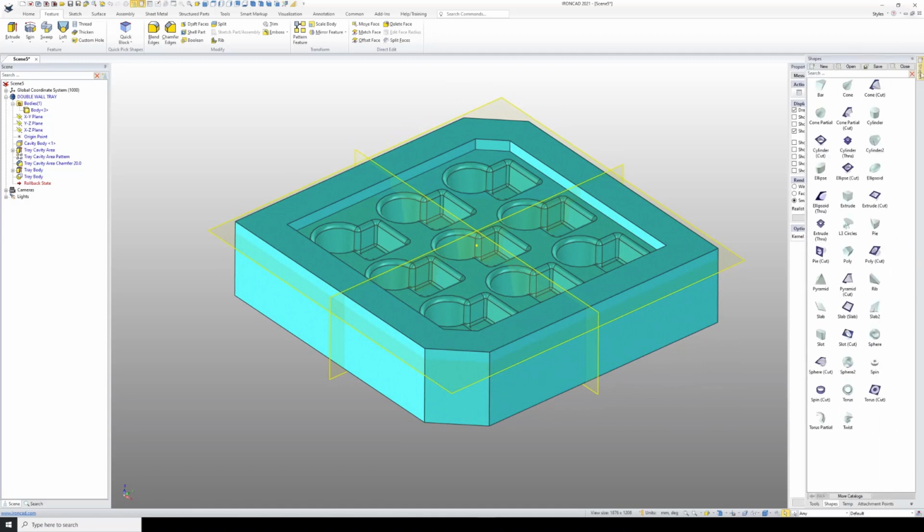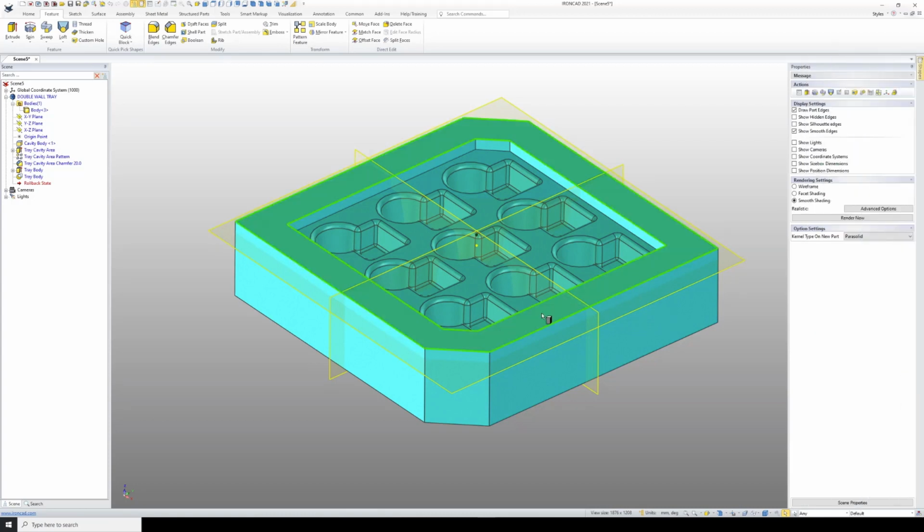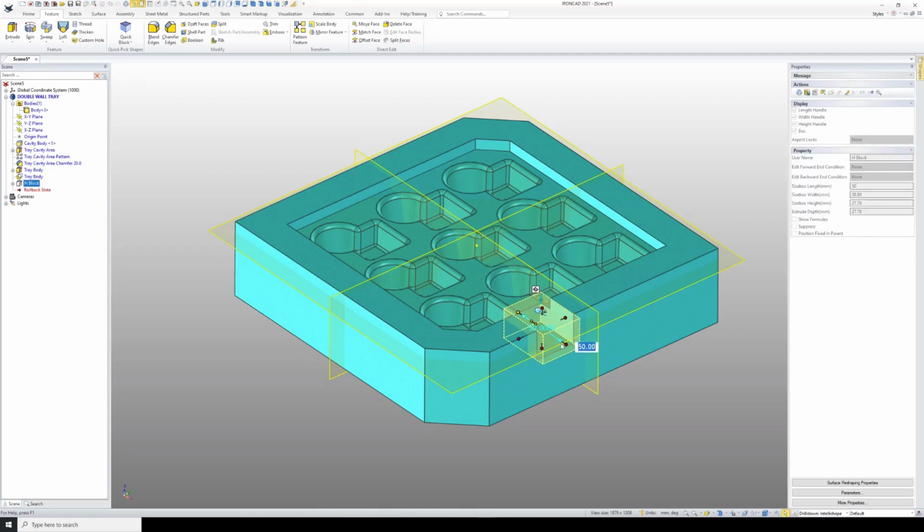And so going to Intellishapes, instead of dragging extrude, I'm going to drag in an extrude cut, and I'm just going to drag that onto this top face, and I'm going to move it, right clicking here to, actually I'll just lock that face in the center, right click, edit position 0, 0, 0,